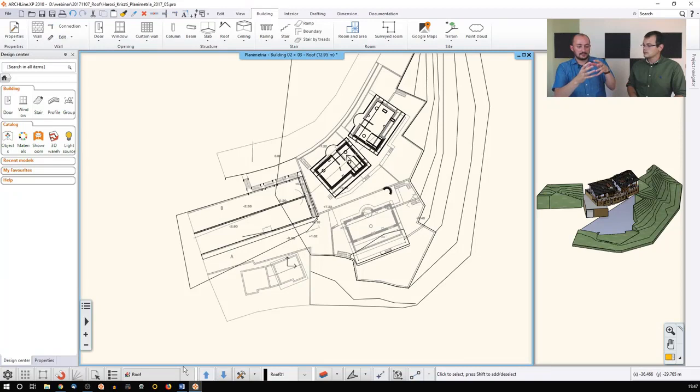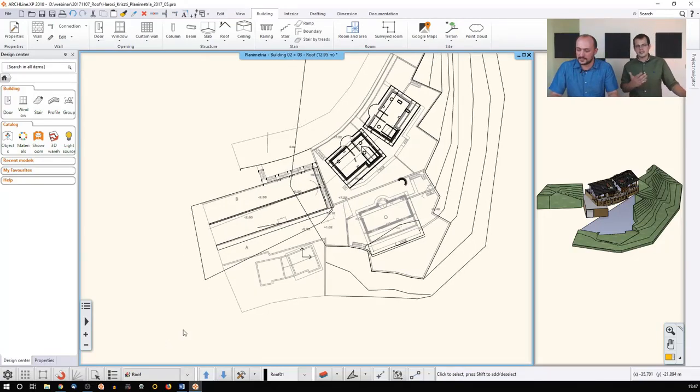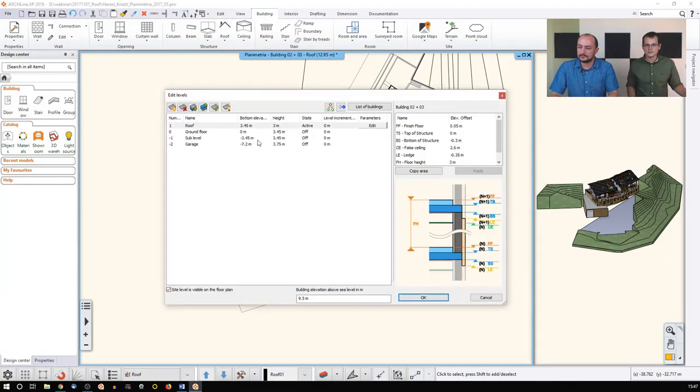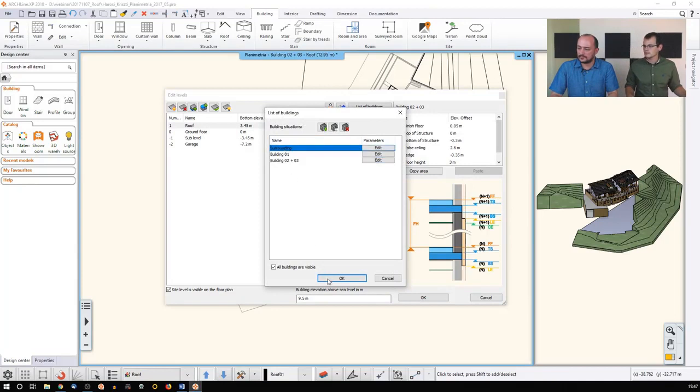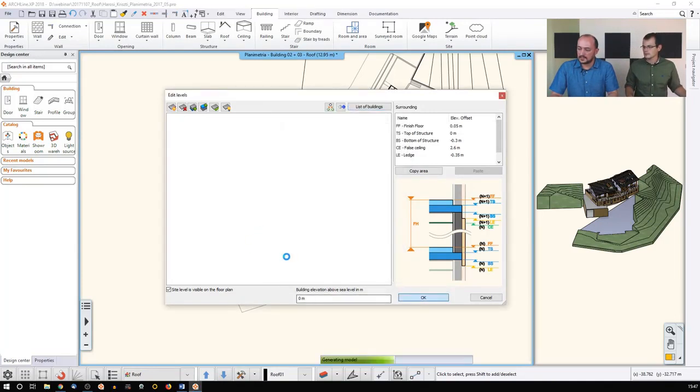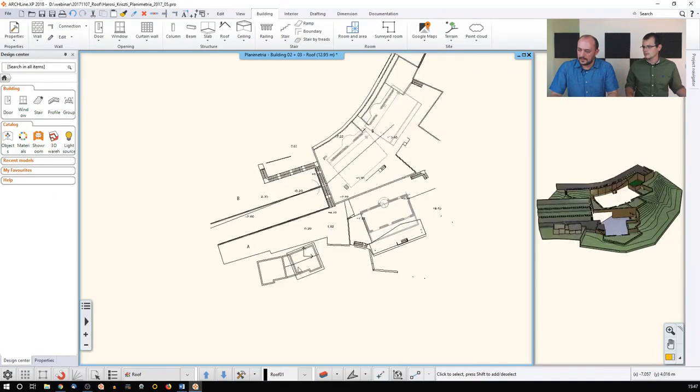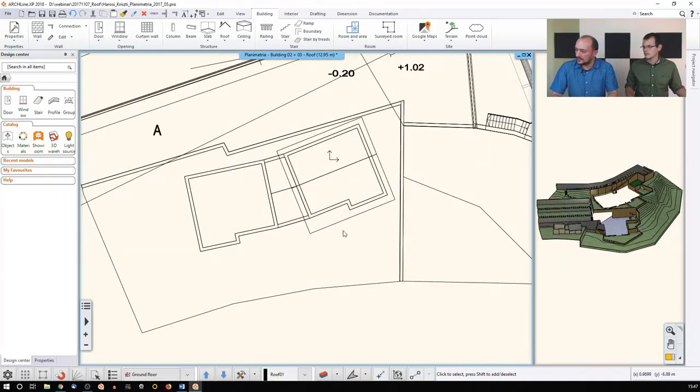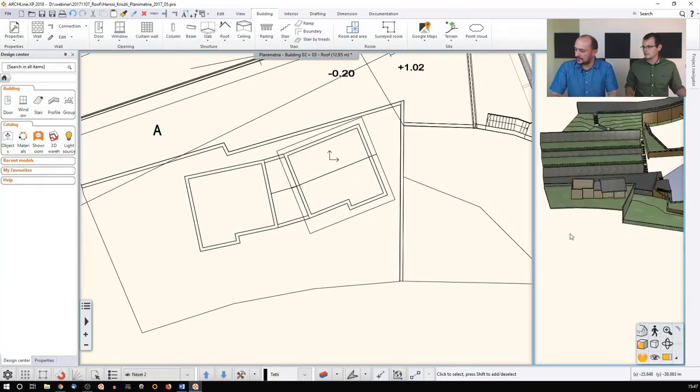you will see it is literally creating tiles themselves, like literal objects as tiles distributed along, and it will make the model quite heavy. It's because it adds a bunch more surfaces. So for this reason, I will just demonstrate it on a smaller roof part, and for that I go back to the surrounding representation and to these small roofs, and I just rebuild the 3D. It's here, and they are there, and that's the roof which I will talk about now.